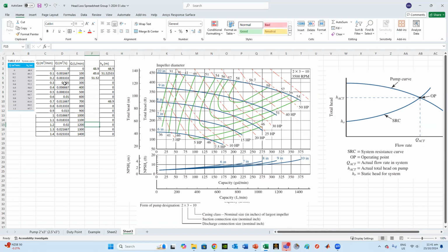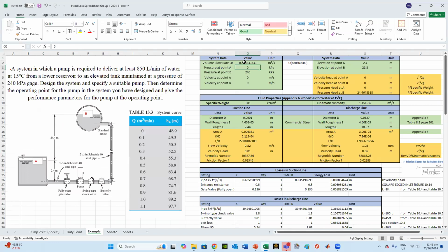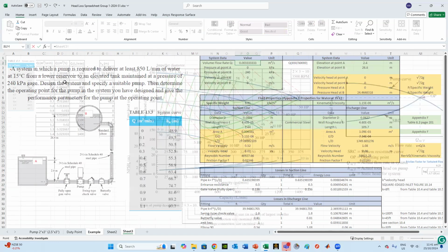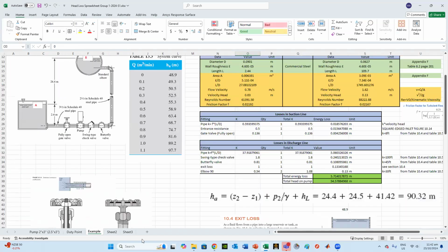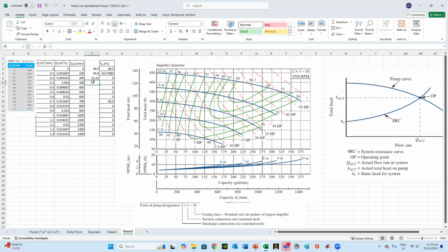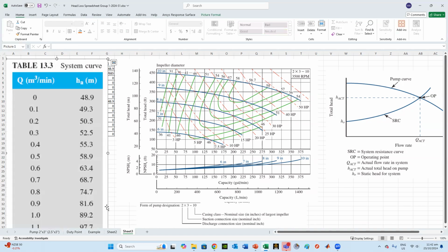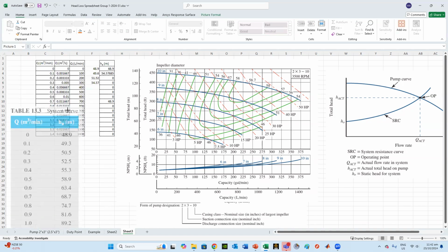And you go to select the third value. See, it's not difficult because I didn't use the Moody chart formula, so that was easy for me. 54.57. So that is just telling you, in the textbook, they make life easy and give you that table, but I'm showing you how that table can be generated.